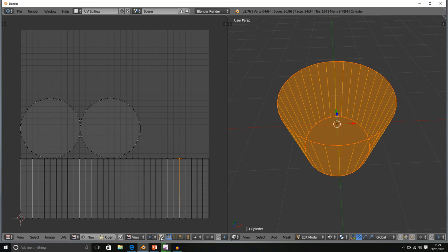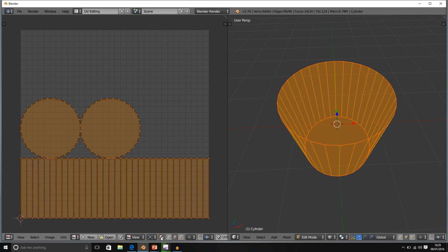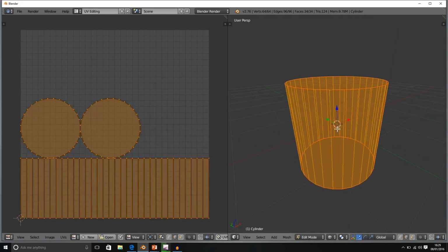All we have to do is click on this button here next to the bounding box icon, which says keep UV and edit mode mesh selection in sync. One left click, and now everything appears to have been reselected. But watch what happens now when I select a vertex or an edge.